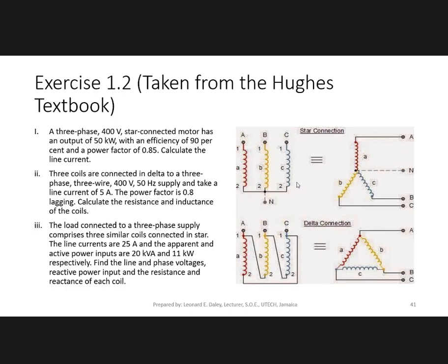These circuits would be what you probably would be seeing on the board in the lab. When we're doing the 2-watt meter lab, we'll be using a delta circuit, and this would be how it would be represented. This would be representing one load, A, representing a load, B, common B, and common C representing a load. And then you connect wires to make the delta circuit.